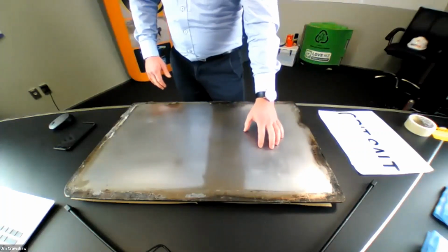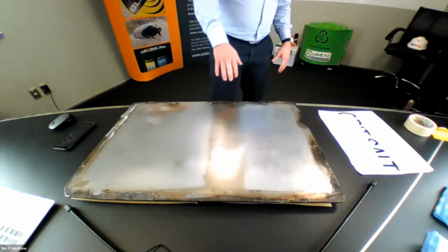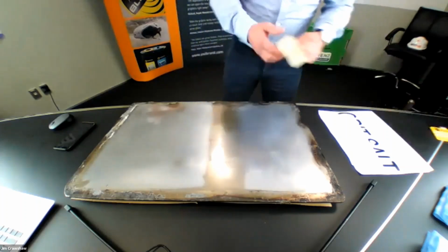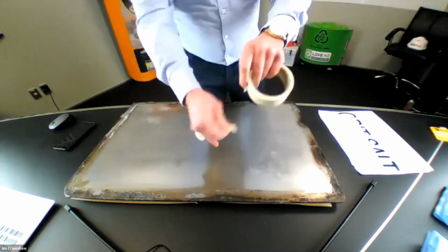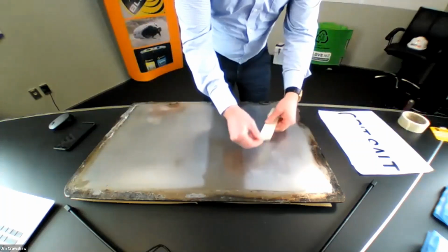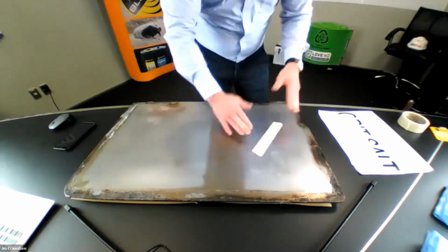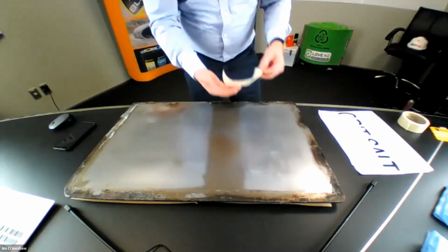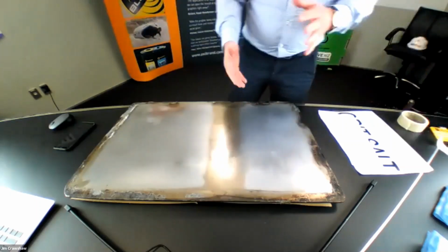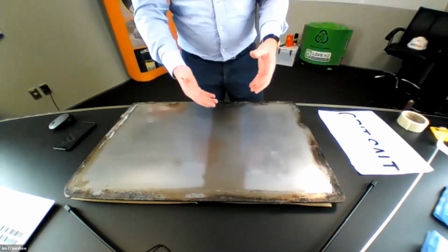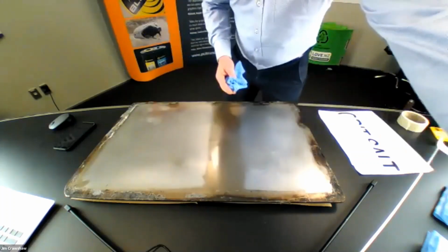What I've done on this side here is I've applied some release agent to it, and I'm going to show you exactly what happens when you do the tape test. Here I've got some paper masking tape, and I'm peeling a bit off, and then applying it onto the mold like this, and you can see it doesn't even want to stick there. I put it down as best I can. It might look good, but it just peels off really simply, no effort at all, hardly any noise. What we want to listen for is some sucking noise from the tape, and see that it's quite hard to pull off.